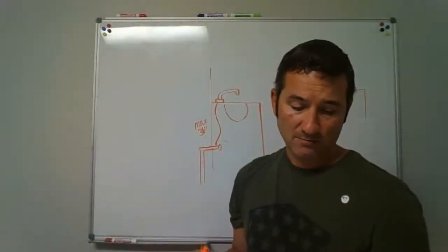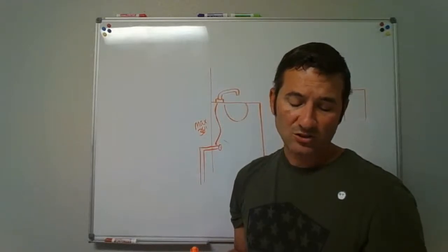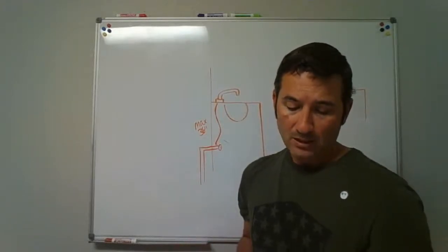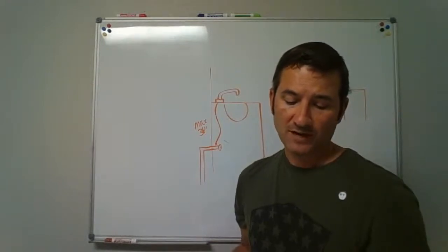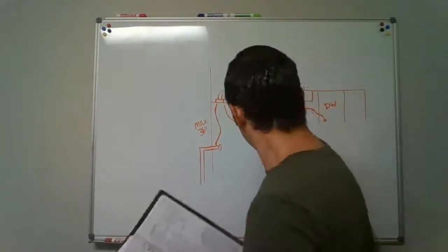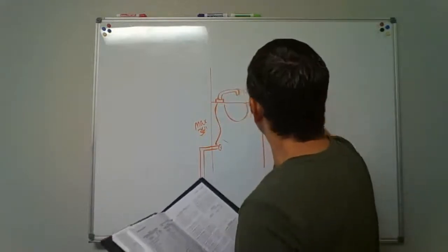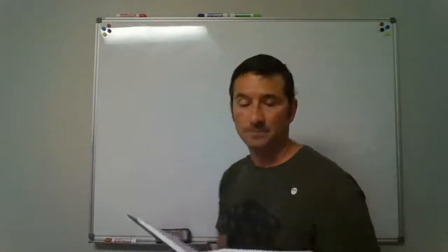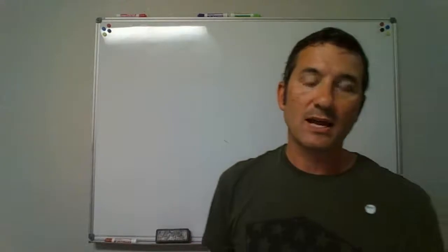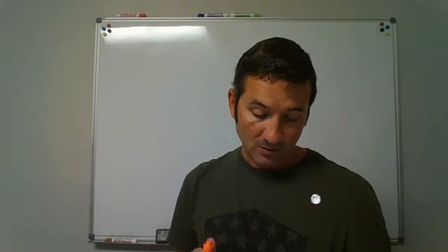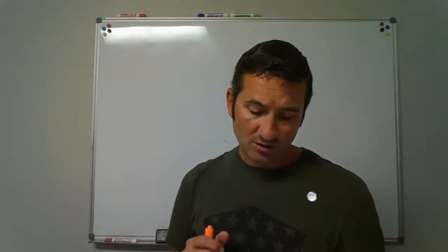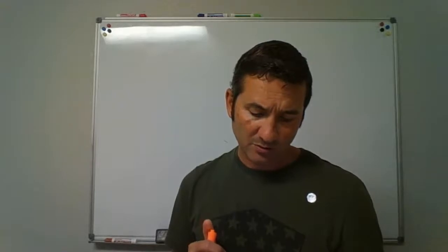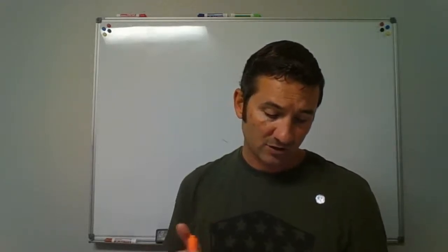Let's see what else we got. Look down to 604.8, water pressure reducing valve. I've asked you about this one several times. So, pressure reducing valve, PRV. When do you need one? When the pressure entering the building is greater than 80 psi. So now you know where you're finding it. 604.8 is where you find that information. Okay. Service lines to sillcocks and outside hydrants and main supply risers where pressure from the mains is reduced to 80 psi or less, or individual fixtures, is an exception to that.